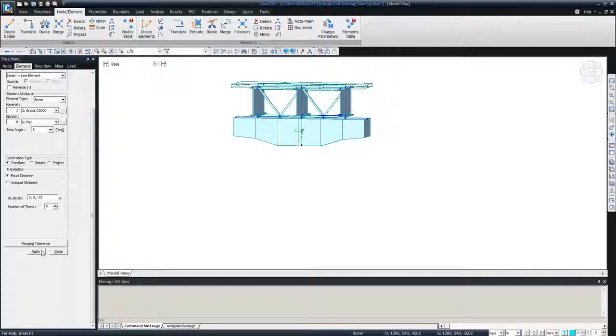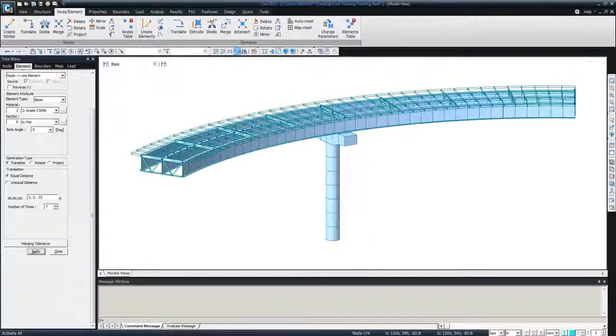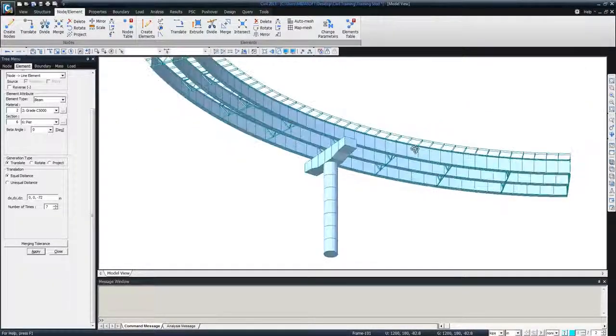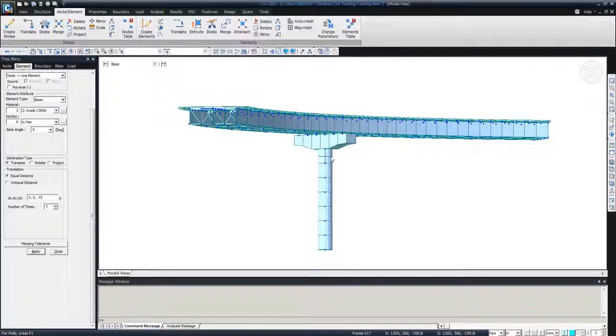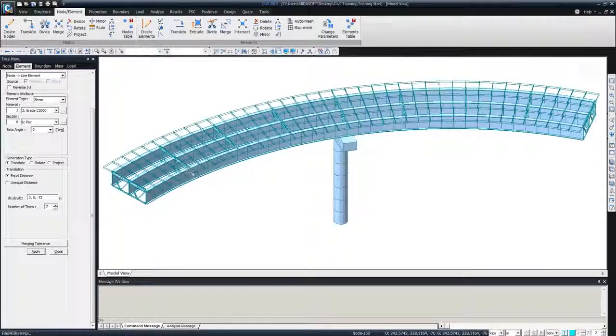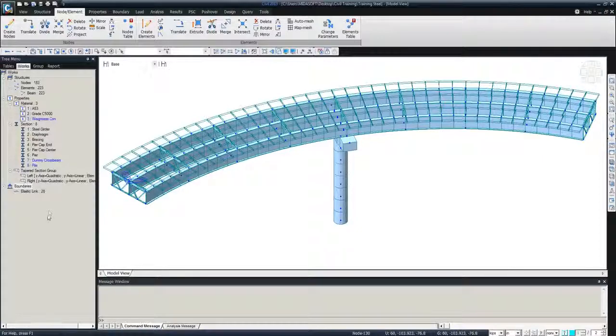And just ensure that it's negative, and going downward is already created. And I can just activate the entire girder. So far I have the girders and the cross frames, and then the pier cap, and then the pier. All right, we just ensure that you save your model from time to time in case you lose your data. Close. And the next part will be modeling the abutments and also modeling those cross frames.